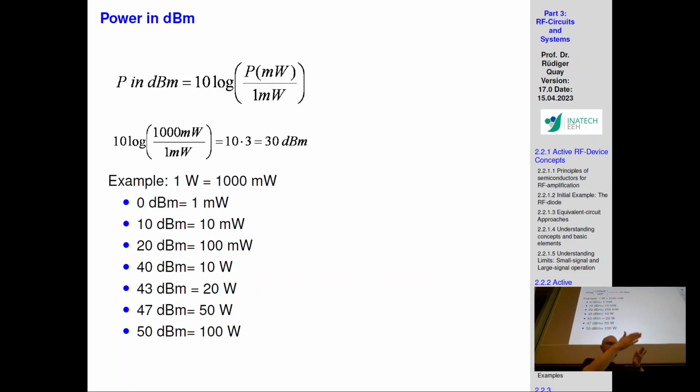one after the other in a daisy chain, because you can't always just shove a huge amount of power and expect that huge amount of power to be amplified by the transistor. No, the transistor at some point will burn down. So you have a low amount of power, and with multiple steps, you go from amplifying it in chunks to a high output power. Either that, or you have the problem that you have a low gain at the operating frequencies that you're designing an amplifier for, so you have to have more of these chunks next to each other.